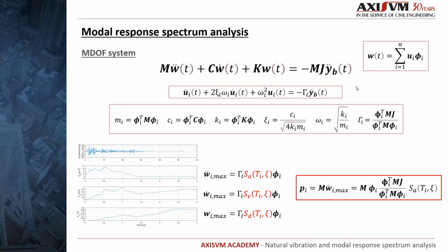From the SDOF system, we already know that the maximal displacement, speed, and acceleration can be defined in advance as a response spectrum. All we need is only the damping and the natural period of the vibration mode. After that, we have to transform back the modal coordinates to get the real displacements, velocities, and accelerations. Once we have the nodal accelerations, the equivalent inertial forces can be calculated using Newton's law. For each mode, we can perform now a simple static calculation, avoiding the need of a dynamic analysis.